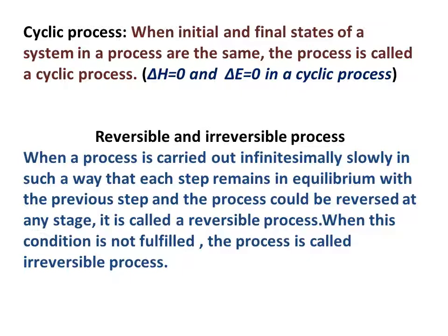So each step should be infinitesimally small, and the previous step and the step you have taken should be in equilibrium. You can reverse it at any stage. Such processes are known as reversible processes, and when this condition is not fulfilled, that process is known as an irreversible process.